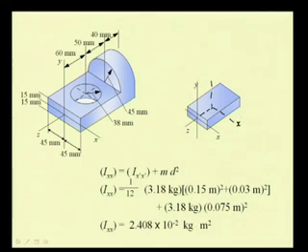So, this is the x prime axis, y prime and z prime the centroidal axes. So, the second moment of this mass with respect to the x axis is equal to the second moment of the mass with respect to its centroidal axis plus m times d square, where d is this distance and m is the mass of this element.